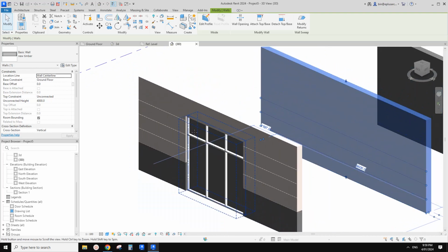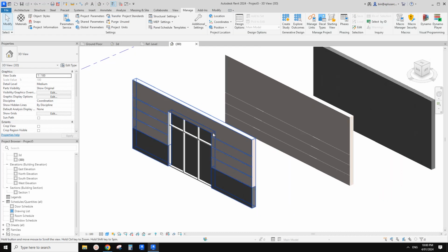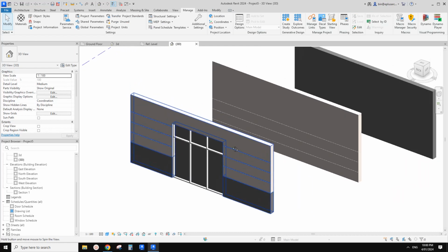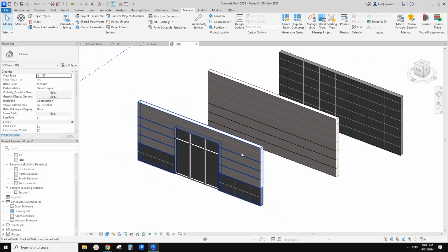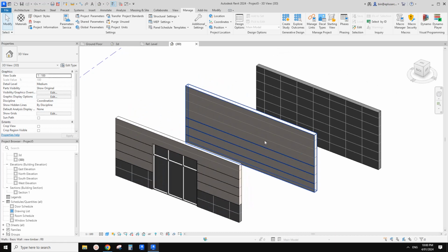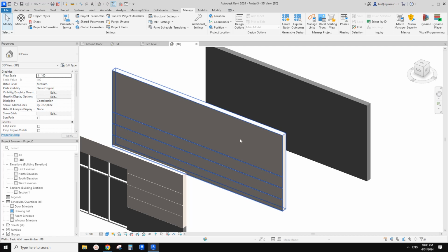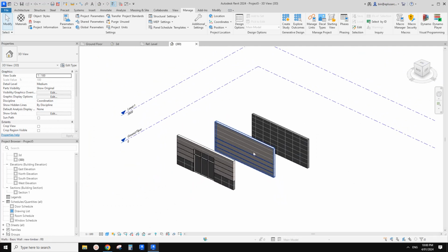But for a real project documentation, I don't think this is a good idea. So I recommend, when you're just doing the working drawings, it's probably better to use surface pattern instead of these voids. Okay, so sorry, reveals.